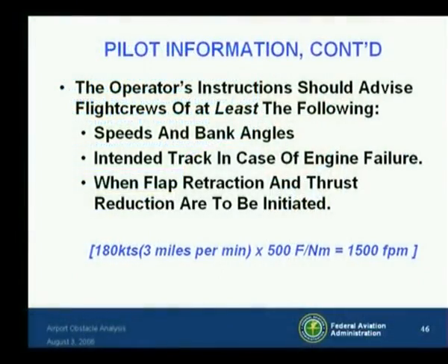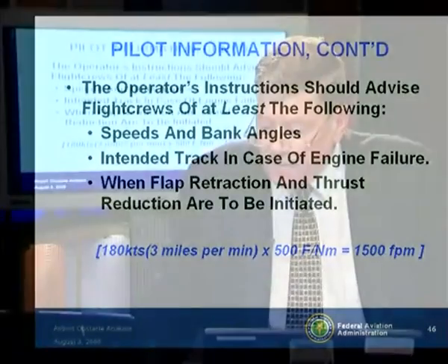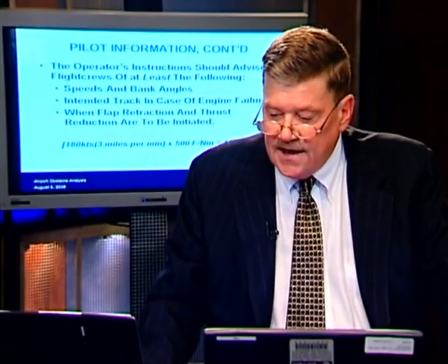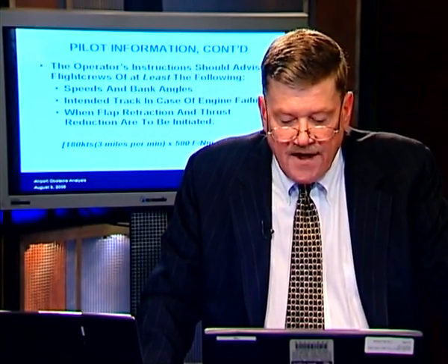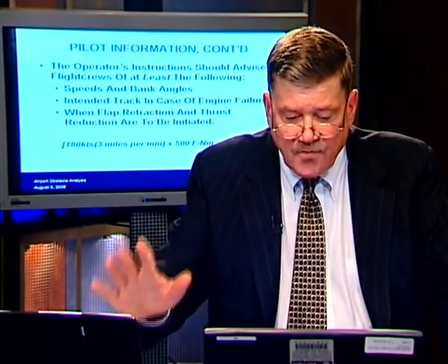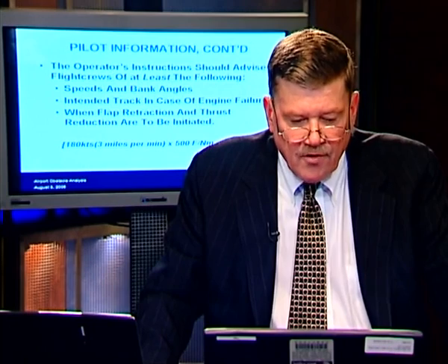And we'll make a note here that operators should incorporate procedures for converting required climb gradients to required climb rates in pilot and dispatcher airplane performance sections of their approved training programs. And this should be done because last time I checked, I didn't have a feet per nautical mile gauge on my dashboard up there. But here's an example of one deal that I remembered.